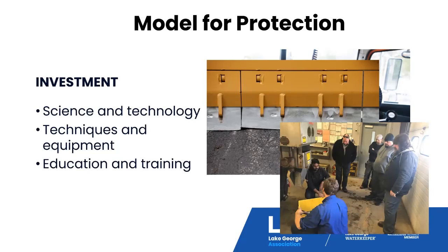And again, I heard Richard mention the white on the roads after. So really, even our drivers are now to a point where they'll patrol the roads after a storm event, take notes on where they actually see that residual salt, and that may actually save them from going out early in the next storm, depending on the size of the storm event, because that residual salt on the road may actually turn into the brine and be enough to pre-treat those roads when the event comes.